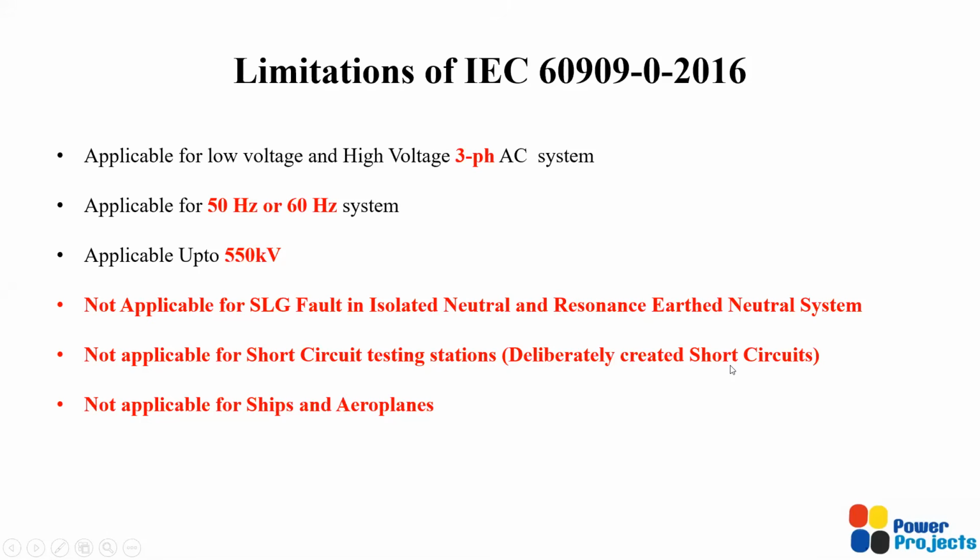If you take, like in India, we have CPRI. Similarly, there is KEMA globally. They have testing stations to test the short time rating of the equipment. There, the short circuit is intentionally, deliberately created. So this standard is not applicable for such testing stations or deliberately created short circuit currents.